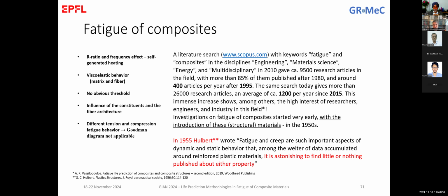And then they're also investigating modeling techniques like S-N curves or constant life diagrams, similar to Goodman diagrams, to introduce techniques that are more appropriate and more applicable for composites compared to what we have already for metallic structures, which are mainly the structures that have received most of the investigations about fatigue.